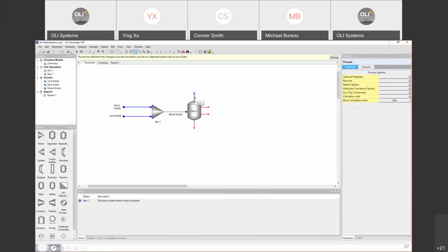And you see that as you put your mouse around this arrow, you will see there is a tag that says vapor, just to make sure that you recognize that there is going to be a vapor only phase. So click on that blue arrow, and then I'm going to put a diagonal here, and then click on the white area to release. That will be your vapor phase.